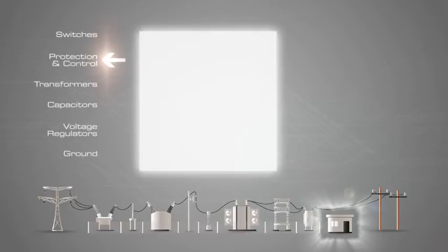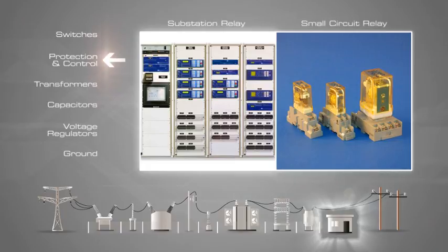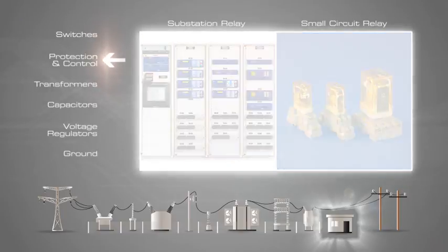A digital protective relay uses a microprocessor to analyze power system voltages and currents for the purpose of detection of faults in an electric power system. The relay is capable of applying advanced logic. It's capable of analyzing whether the relay should trip or restrain from tripping based on current or voltage magnitude, parameters set by the user, relay contact inputs, and in some applications, the timing and order of event sequences.